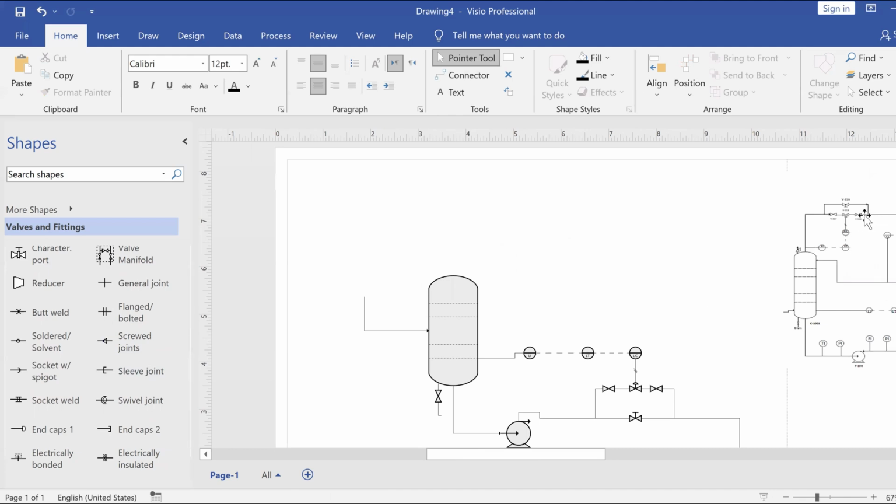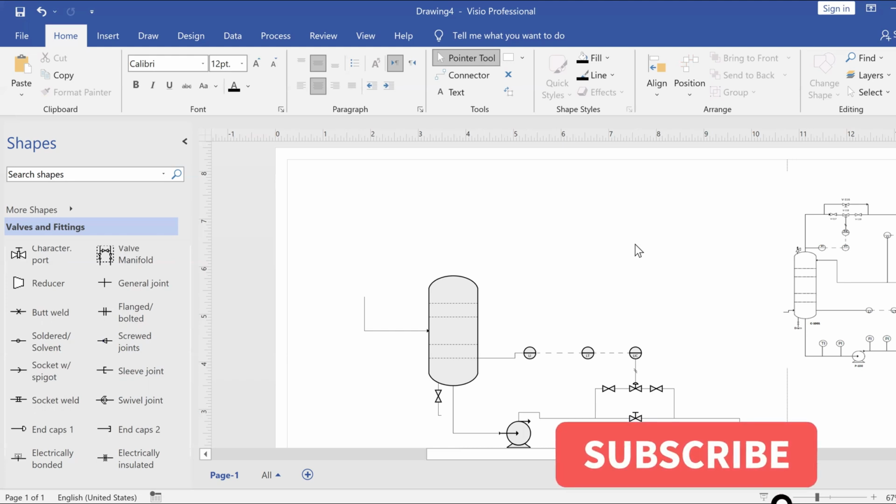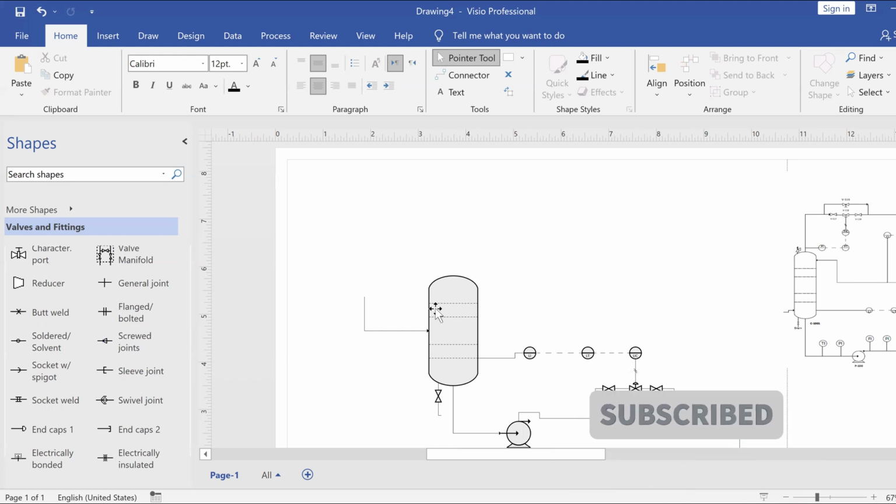Next, let's talk about this. This loop is a pressure control loop. So whatever is leaving the top of the absorber is actually a what? It's a gas. So if the amount of gas inside the absorber is way higher than normal, it's obviously going to increase the pressure inside the absorber. So this is why the pressure control loop is on the top of the absorber.